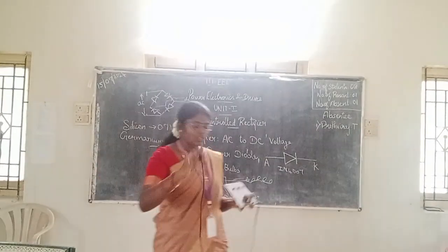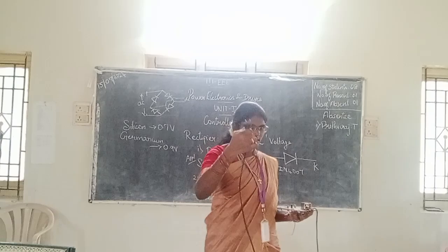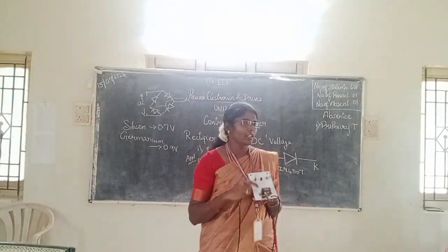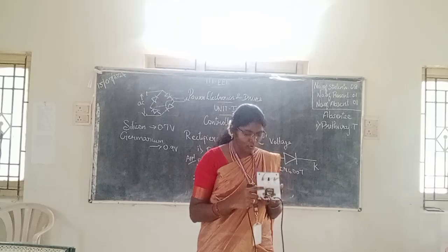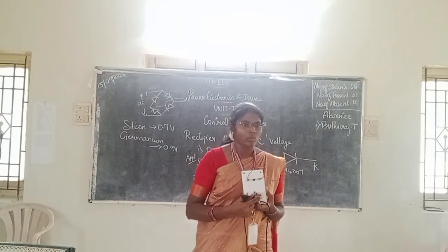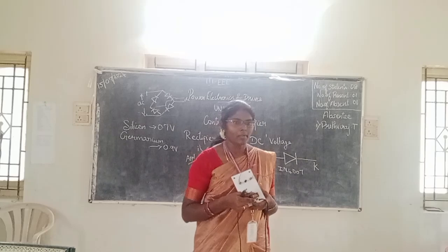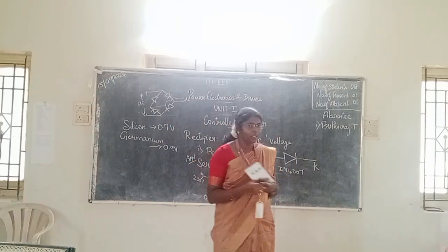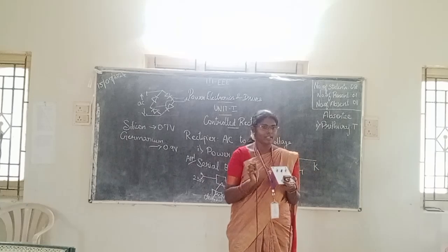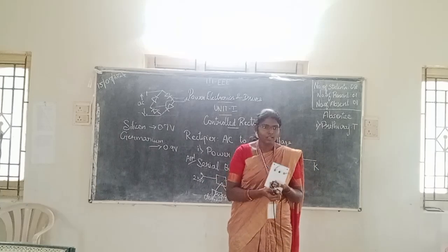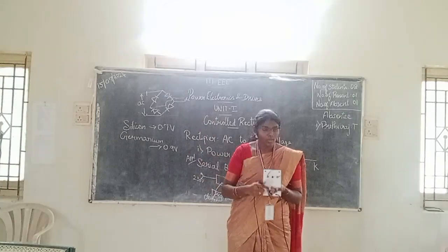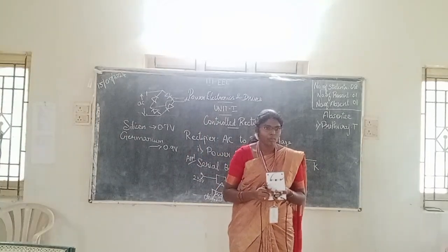So I told you, right? Here we are giving an input AC supply. So this is 230 volt. Okay. So for 230 volt you will have a small transformer. If you note down here, we will be writing it as 9 volt. Small transformers are available in 9 volt, 12 volt, 24 volt, whatever is required for the electric devices we are going to operate. Based on the requirement, transformer ratings are available. So whenever we are giving this AC input, what is the function of the step down transformer?